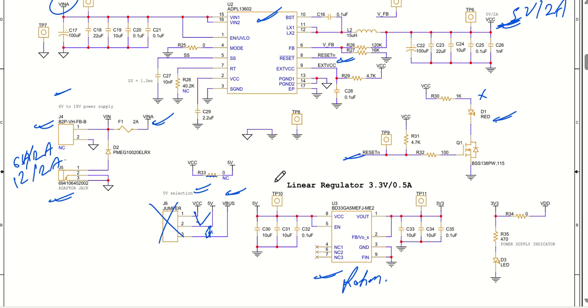So hope you guys are clear with the microcontroller power supply management, and here even the 3.3 volt indication is given by one of the LEDs. Now, VCC and 5 volt are being used interchangeably, so that's not a problem. And 3.3 volt will also be named as VDD. So 5 volt will be used as VCC as well, and 3V3 will be used as VDD. So that is to be understood.